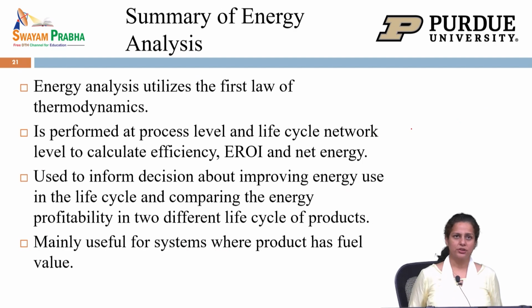In summary, for energy analysis, simple energy analysis looks at the flows that are related to energy products, and it utilizes the first law of thermodynamics by balancing the input energy equal to output energy. Of course, there is a lot of energy that is going to waste. So, our efficiency of the process is never equal to 1, it is generally less than 1. The closer it is to 1, the more sustainable it is. We can perform this energy analysis at process level and life cycle network level to calculate efficiency, energy return of investment and net energy.